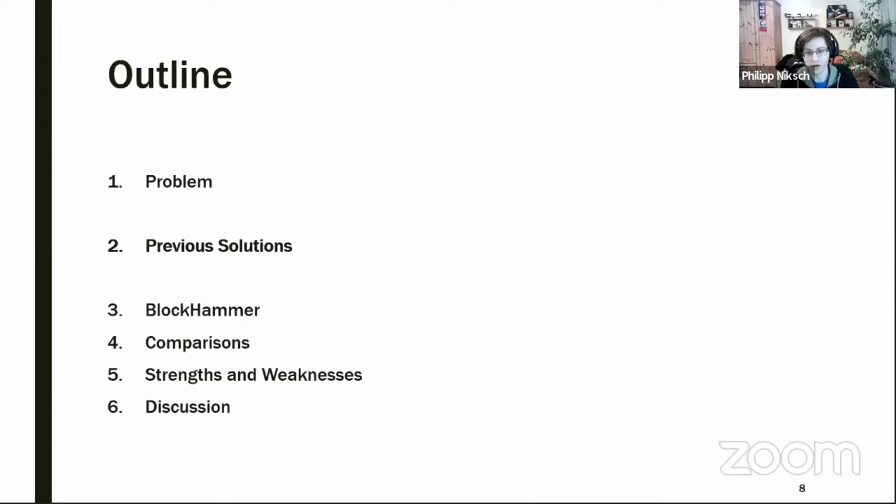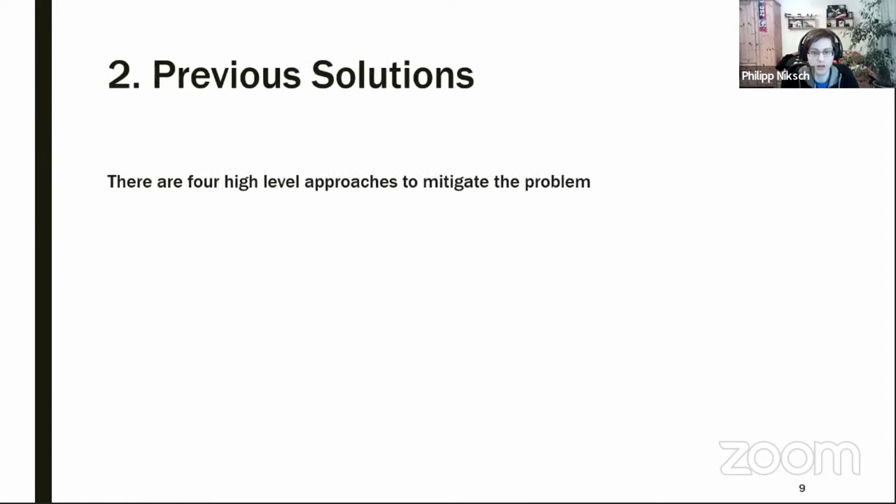Since RowHammer is a major concern, there have been many proposed solutions in the past. The paper acknowledges four main ways to mitigate this problem. First, and maybe the most obvious solution, is to simply increase the refresh rate. If increased far enough, an attacker cannot hammer enough times to make a cell unreadable before it gets refreshed. The obvious problem with this solution is that while not under attack, the memory is getting refreshed unnecessarily. This wastes both time and energy.